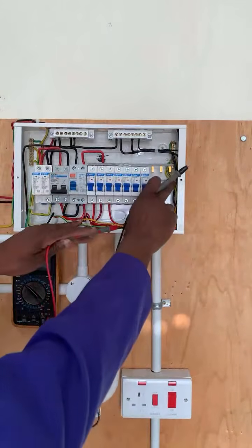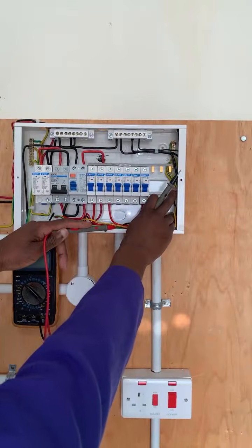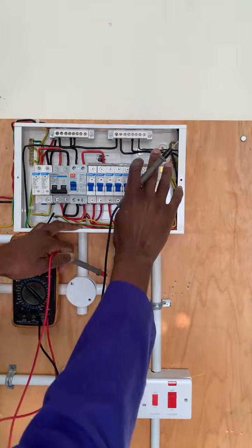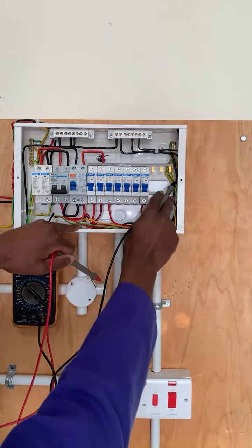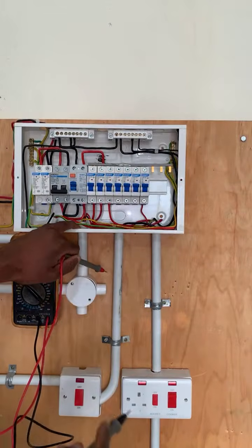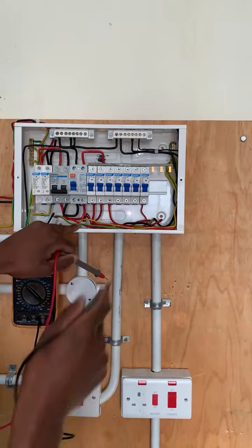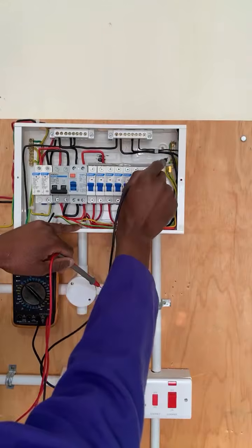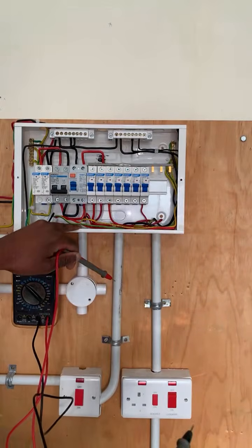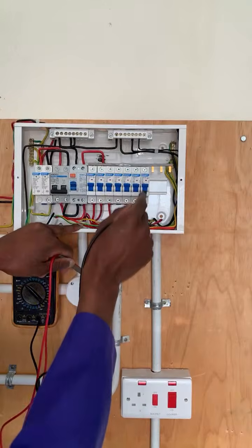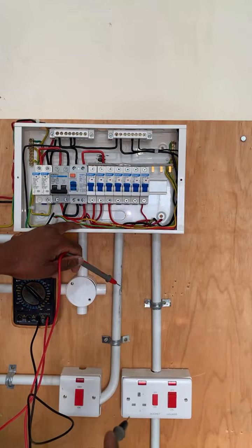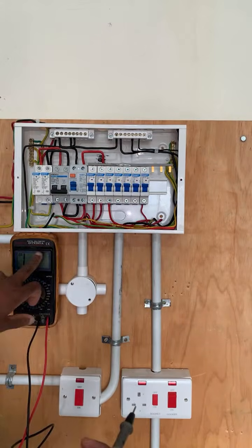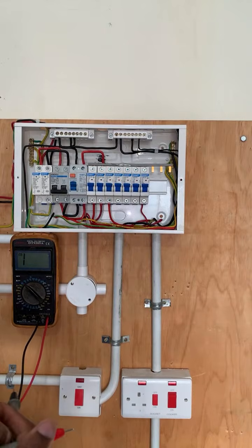So we have installed the light earthing right there. So the worst thing that can happen is to have a short circuit between the earthing and the line or the phase. Another thing that could happen is to have connection between the neutral and the earthing. That is faulty. Another thing is the neutral and the line or the phase. That could trip the MCB because that's a short circuit. If we get that beeping sound and those figures on the screen, it definitely means there is a short circuit.